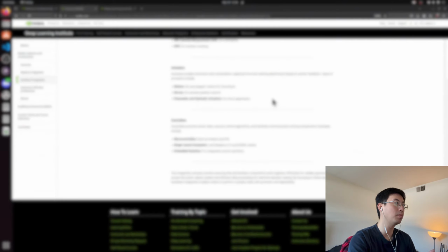And for some robots, they have actuators. Actuators are like motors, so DC motors, stepper motors, and you have servos. Servos have more position control, whereas a DC motor just spins around without even knowing how much it has spun. And you also have pneumatic and hydraulic actuators for force applications, stronger grip, right? You can use pneumatic or hydraulic actuators, like in a robot arm.